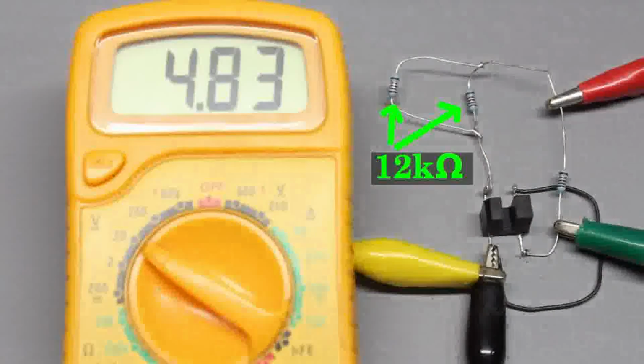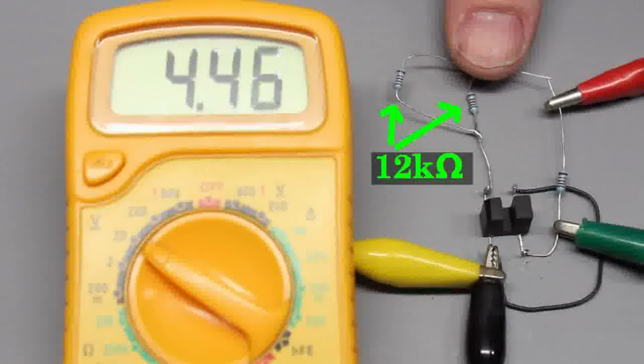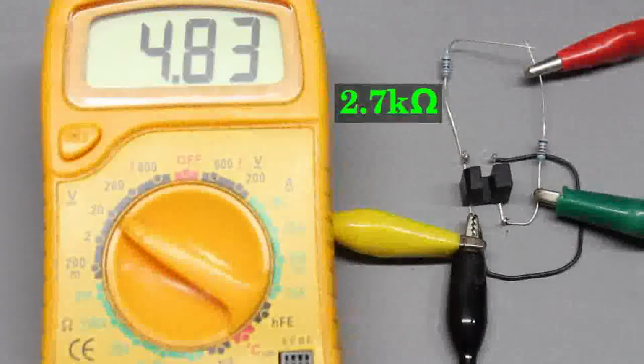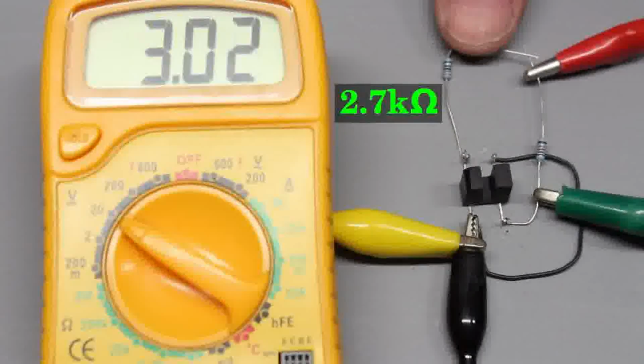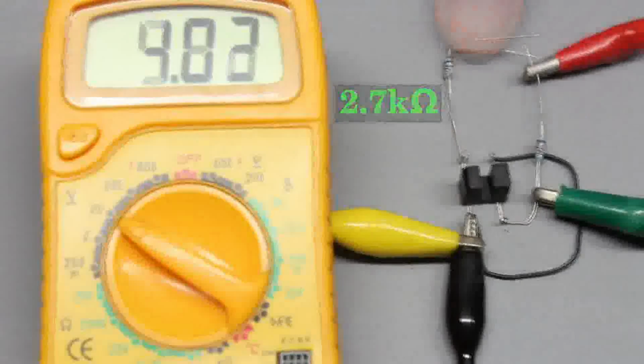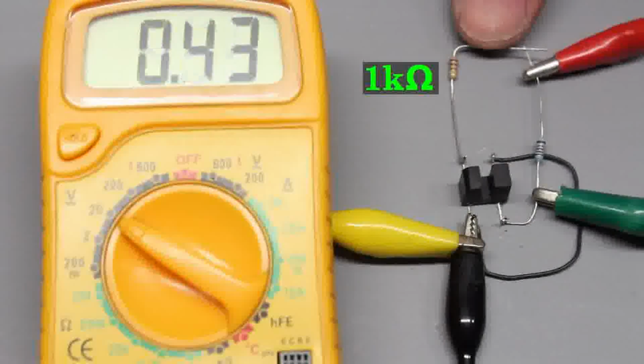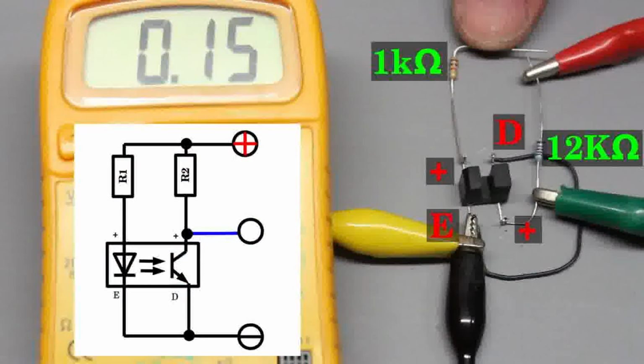With the LED turned on, the voltage across the receiver should drop clearly below 0.5V. The value of the series resistor on the LED side is lowered, until we get a reading of 0.15V with a 1 kiloohms resistor. With the 12 kiloohms resistor on the receiver side and the 1 kiloohms resistor on the LED side, the device can be operated at a 5V DC power source.